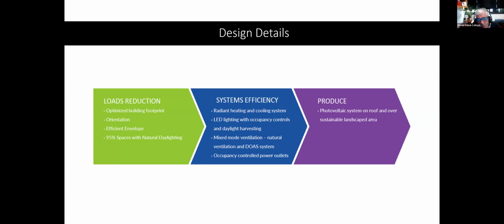In order to decide on the system: it has a radiant heating and cooling system, so it has coils in the floor that hot water or chilled water pass through, and this is how they heat or cool the building. It has fans also to recirculate. Fans have a low energy consumption cost. So if you can use a fan to recirculate the air to make the temperature uniform within the room, then that is the best option you can have.